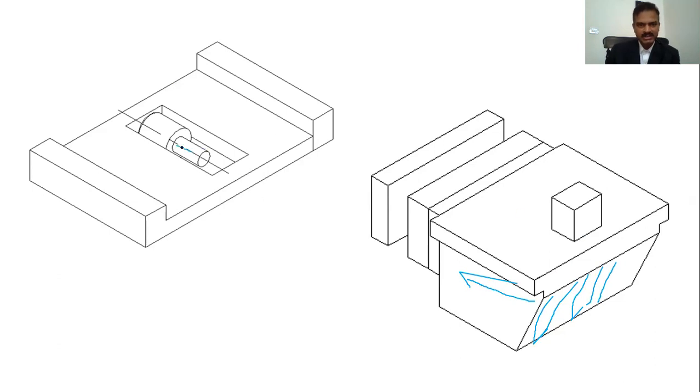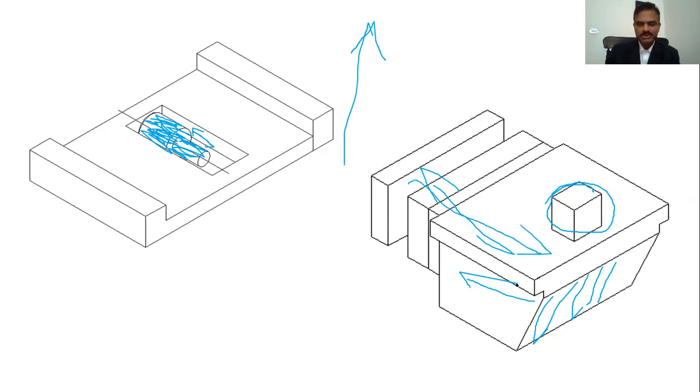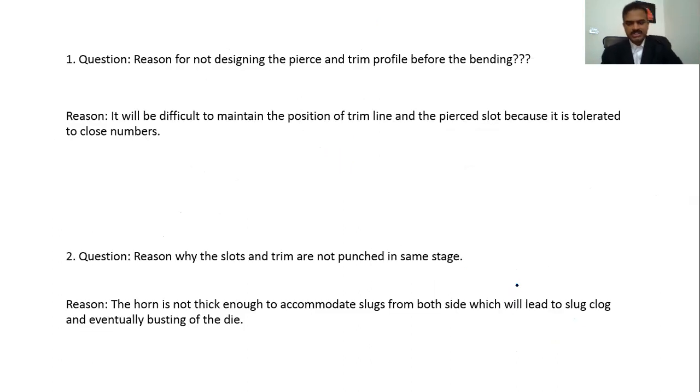This little gas spring here, which is mounted inside the U channel, will be pushing against this post here. Just imagine when it is flipped upside down, right? When the cam moves forward, this piston-like thing will be pushed inside, and it will be under pressure. And when the cam goes back up, this is going to push this post, and eventually this cam is going to go back to its original position.